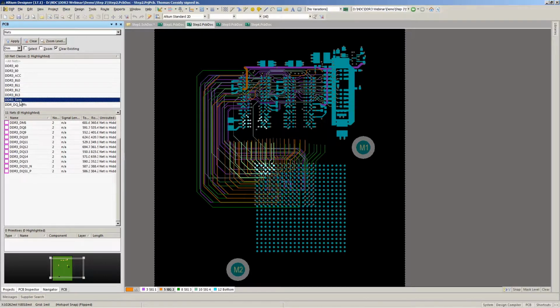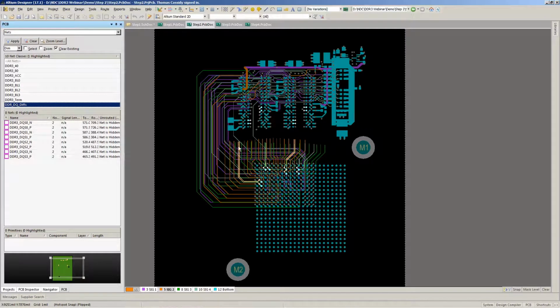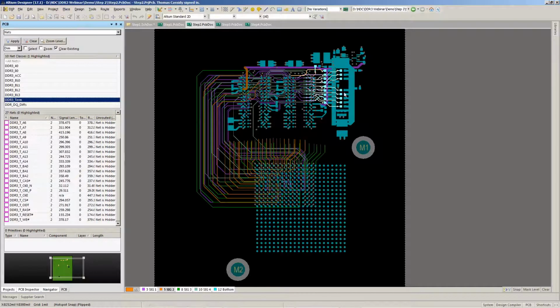And then I've also got my clock signals coming off. I haven't routed them yet, but I did a breakout. And then also I've routed my termination from the second chip over to my termination resistors. And this is derived from our previous design, so I kind of already had the termination layout. One note here though is you want to make this as clean and solid of a plane as possible. So I basically got my power supply up here, and then I've got a nice, well decoupled path for my resistors, and then the decoupling capacitors are spread around on the top and bottom layers. So you want to keep your termination as clean as you can with decoupling.